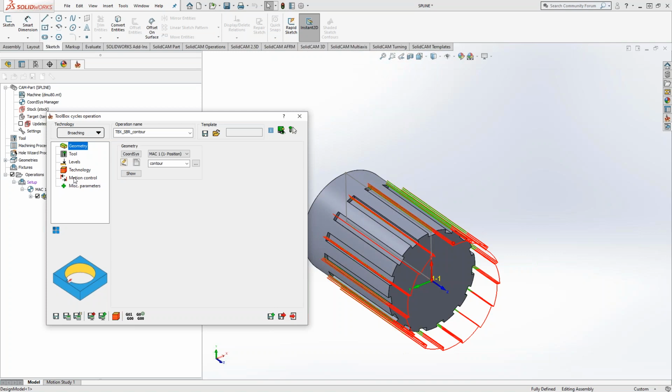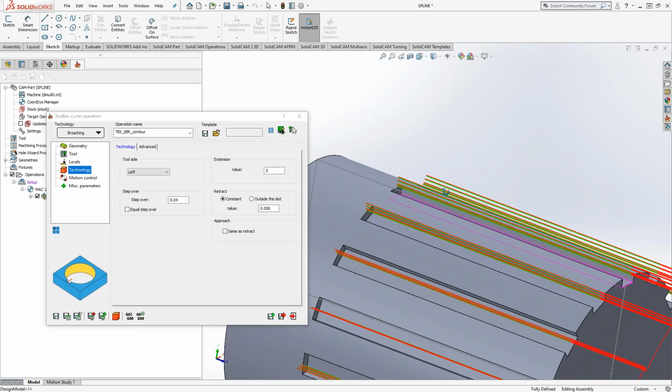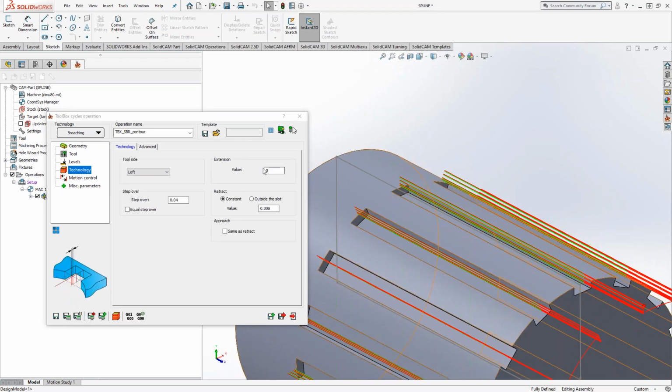Let's say that. And with this entire broaching operation here, like Mark said, usually you have a relief or an open end. In this particular case, it's closed off. And maybe Sultan, do you ever have a part where it's blind like that? Because I guess what we could do is tell the developer to add an arc in there, like in the profile operation and the link section, so you can actually arc out.